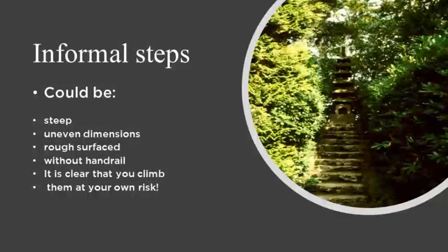There is no specific control over external steps in private domestic gardens, provided they are detached from a building and do not form part of the access route to the house front door. But there is always, of course, a legal obligation to design safely. Natural stone steps, created as part of a rockery, might justifiably be rugged, uneven and steep. But don't mix formal and natural steps to catch the user unawares. In this seminar, I am mainly concerned with formal flights of steps.